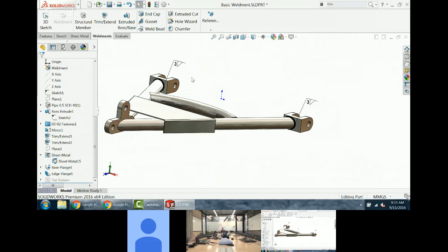But if I want to export it to ANSYS, then I'd have to go in and make stand-in parts. So you could do the fillet bead for that if you're going to be doing that. You'd probably want to do a configuration with that, just so you have one configuration that's fully loaded for FEA, and then another configuration that's easy for you to get a clean cut list out of.